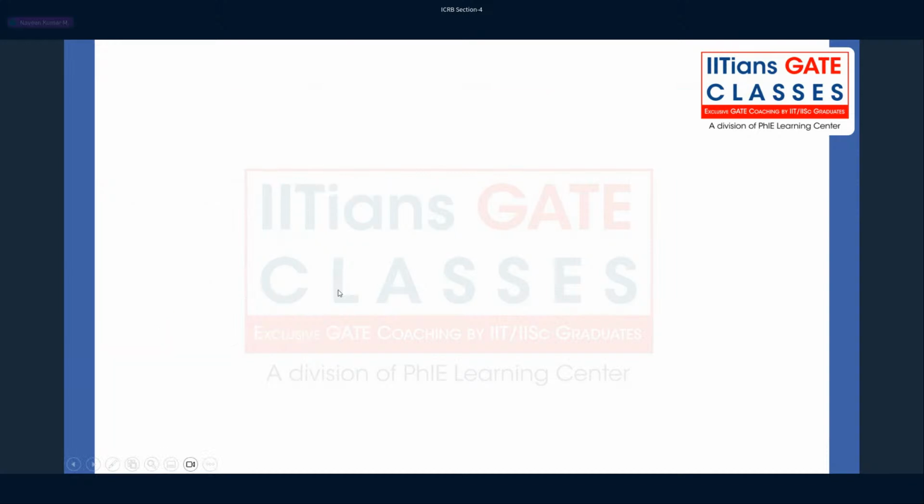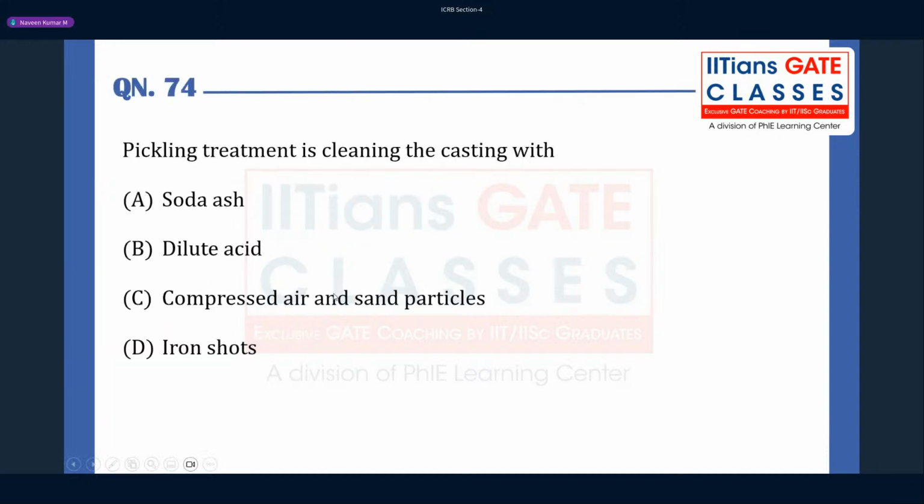Okay, next. Pickling treatment is cleaning the casting with... So actually, the casting can be treated with so many things: soda ash, dilute acid, compressed air, and sand particles in shots. The last two are not for pickling. Yes, they are for cleaning, but from a mechanical perspective. It's not pickling.